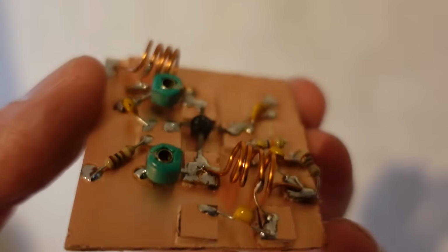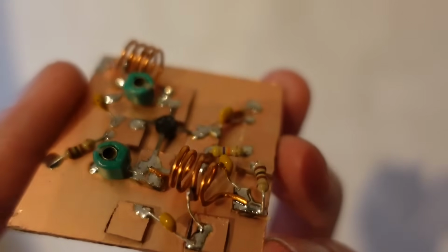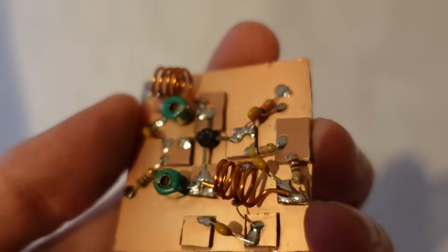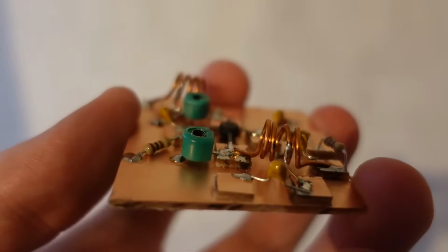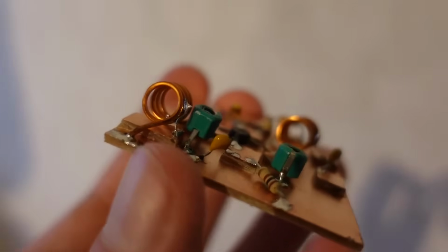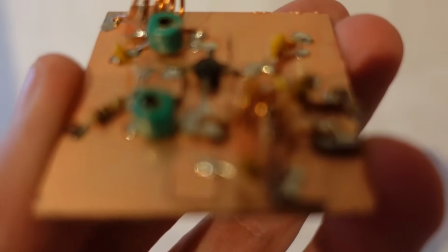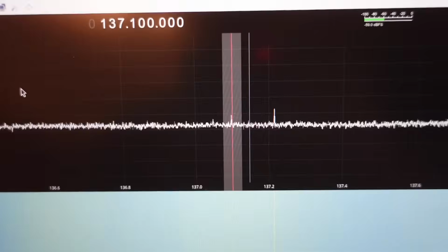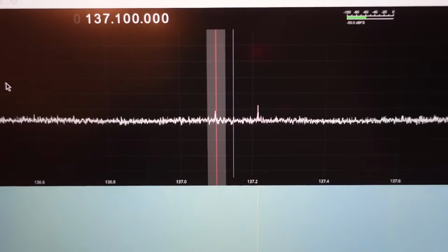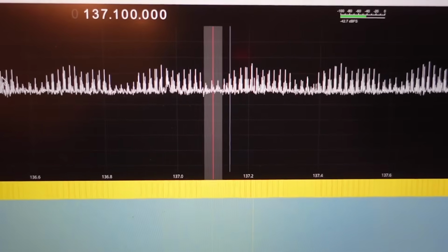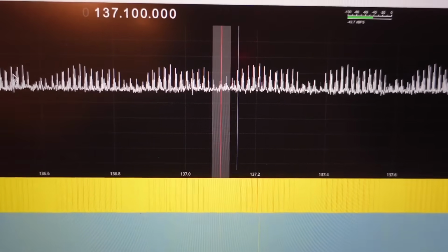This design also uses these weird coils that are tapped off one turn into them. And I guess this just shows how normal intuition falls apart when you're dealing with RF. The antenna input and ground go to the same coil, separated by just one turn. And somehow this doesn't kill the signal, which is very weak. This thing is supposed to amplify everything by 20 dB, and looking at it with a modern SDR dongle, it looks like it does. So hopefully this is all I need.